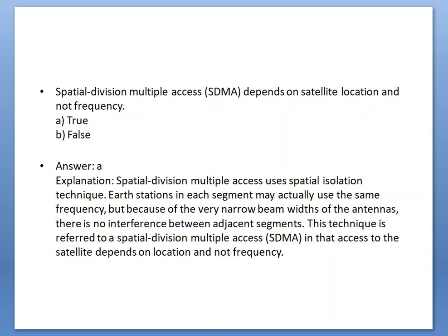After that, we discussed a few topics based on satellite repeaters, including non-regenerative repeaters used in satellites. We also derived the formula for the received power PR and the ratio of received power to noise. We also analyzed satellite repeaters with 10 users, with an uplink frequency of 375 MHz and a downlink frequency of 275 MHz, with 22,000 nautical miles as an example.